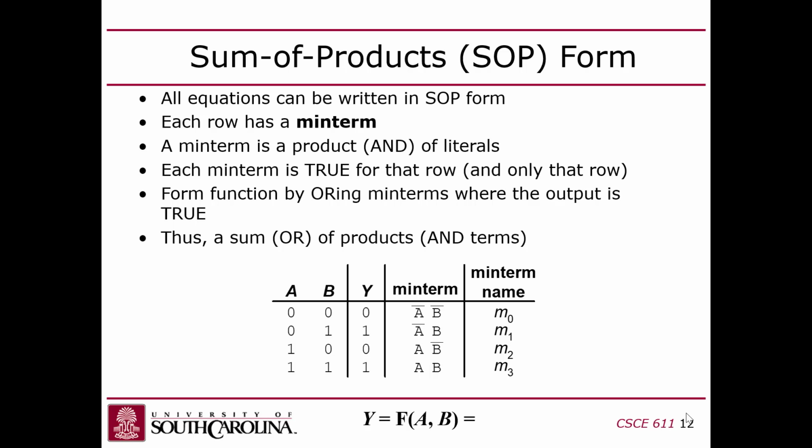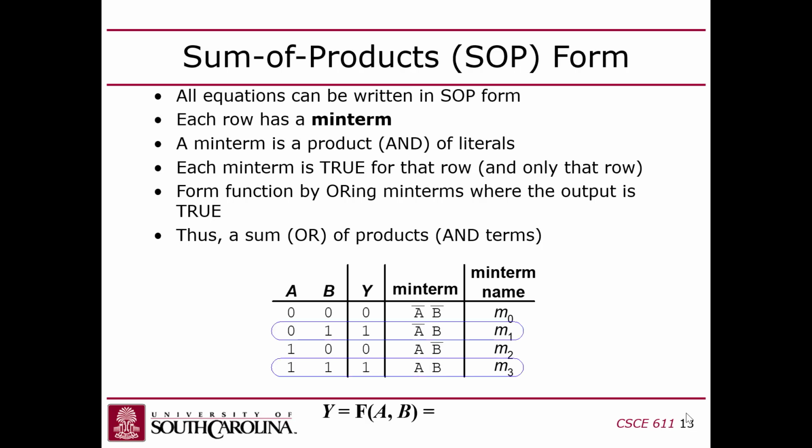So I guess what I'm trying to say is, I don't think I explained that very well, but when you write code in Verilog, SystemVerilog, VHDL, or any of the HDL languages, generally speaking, the compiler is converting your code into Boolean. And then it processes that Boolean using heuristics that try to minimize the logic or map the logic. I gave you an example of mapping last time, right? But that's done in Boolean expressions. It never generates a whole truth table. That's not practical. Okay.